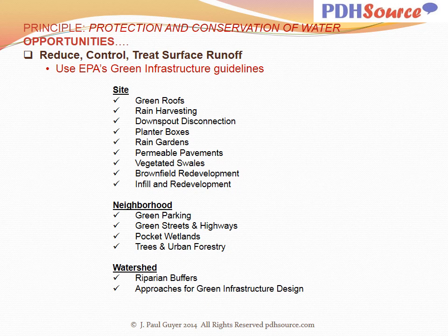And as originally developed, the gutter downspout features just discharge the water to grade around the building. But if you go to a little bit more expense and channel that rainwater into a storage facility like a tank or even just a barrel and capture that storm water, it's high quality water, and you can save it and you can use it for landscaping purposes, irrigation purposes during the summer when you need it.